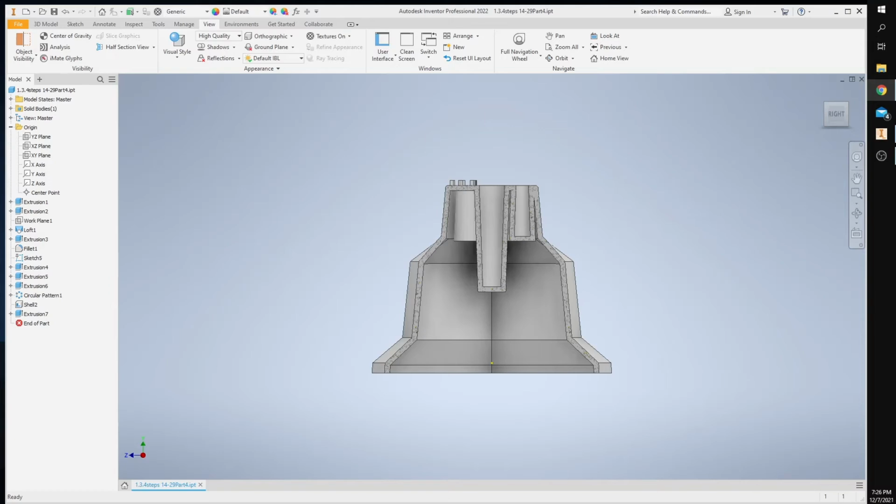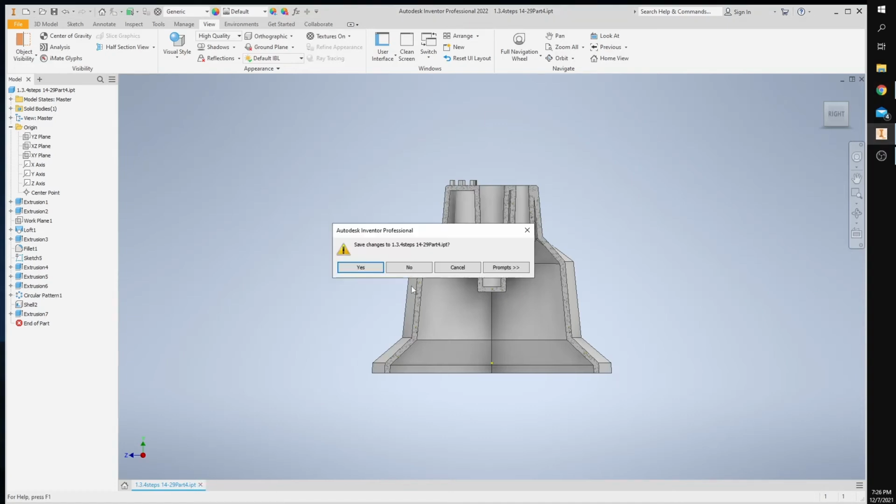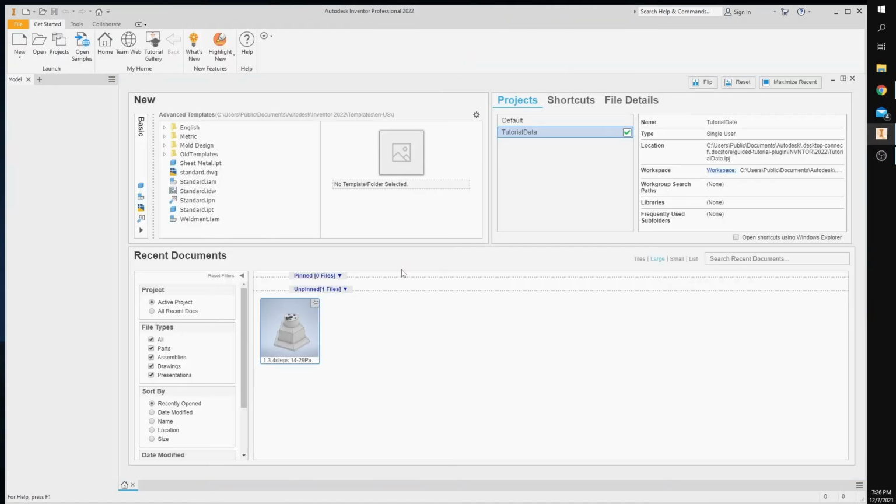So moving on to steps 10 and 11, it's asking us to revisit the crank arm drawing that we did in 1.3.5. That's the VEX part that was used for the Tramotoy, the crank arm. It's asking us to replace the right side view with the section view, increase the scale of the section to make it bigger, and add some annotations if necessary, and also on letter B to add dimensions to fully detail the part. So what I'm going to do is X out of this and close this. I'm not going to save my changes.